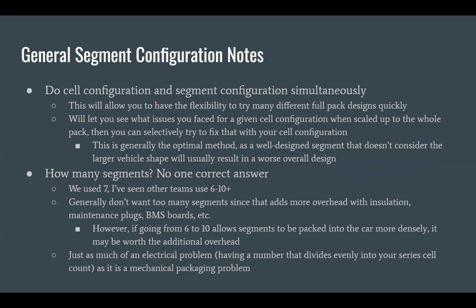You actually got really well to one of the questions in the slides. When you're going into your general high level segment design, vehicle design, how many segments do you want? The answer is that there isn't necessarily a correct answer. A lot of the best teams that I've seen are running a configuration that uses 6 to 8, but we've seen designs that go up to 10 or 12. Obviously the main thing you have to consider is that you have these energy and voltage limitations: you can't go above 120 volts in a segment, and you can't go above 6 megajoules.